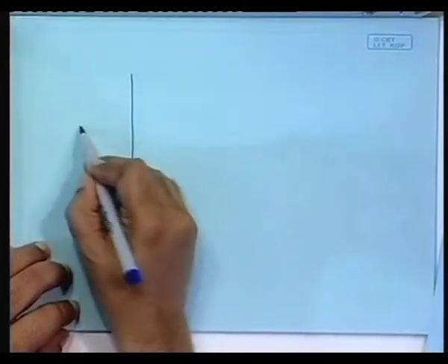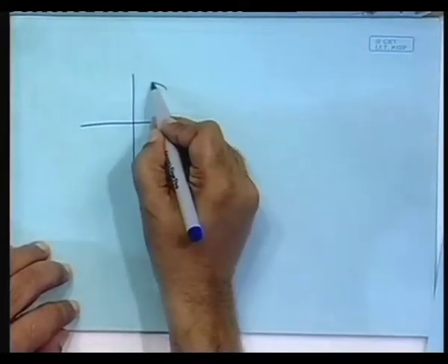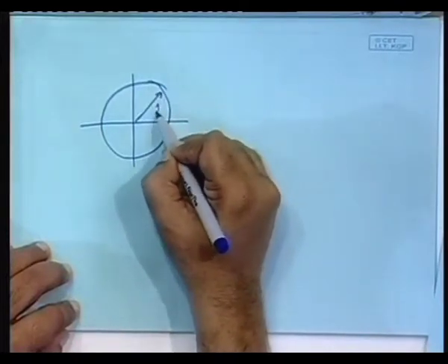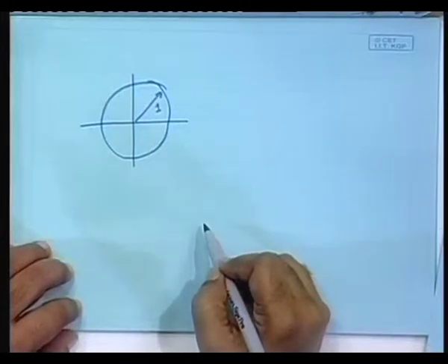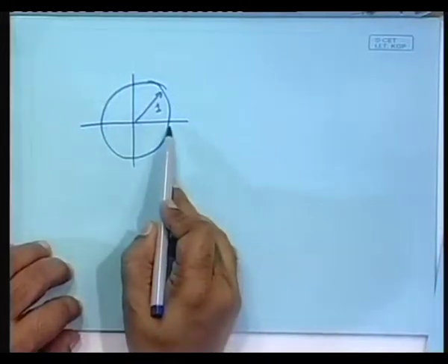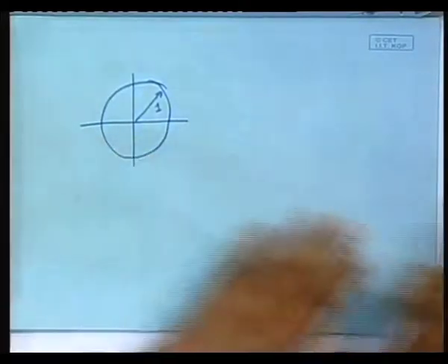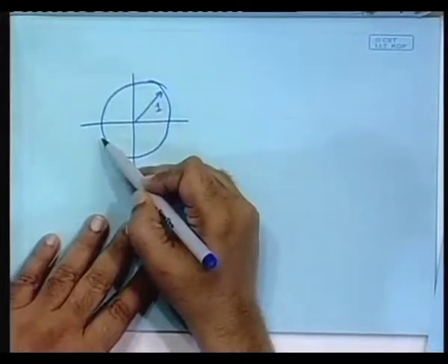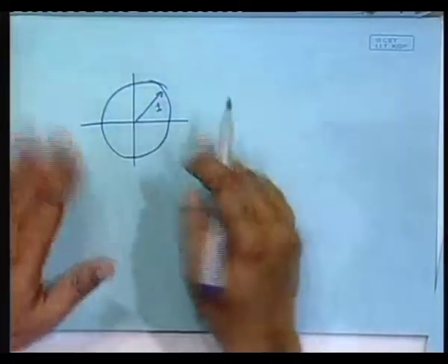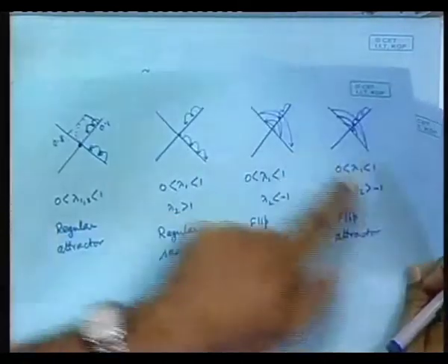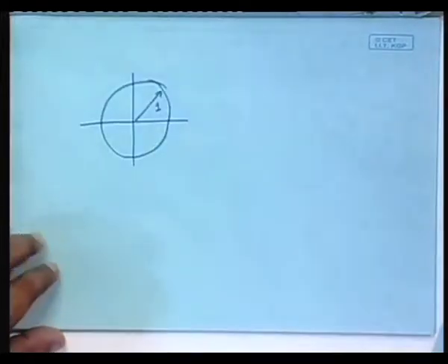So, actually it will boil down to whether or not the vector itself, that means the complex number itself, is inside or outside the unit circle. Okay. If it is outside the unit circle, it will be unstable, but you can now relate the positions of the eigenvalue on the unit circle to the behavior.